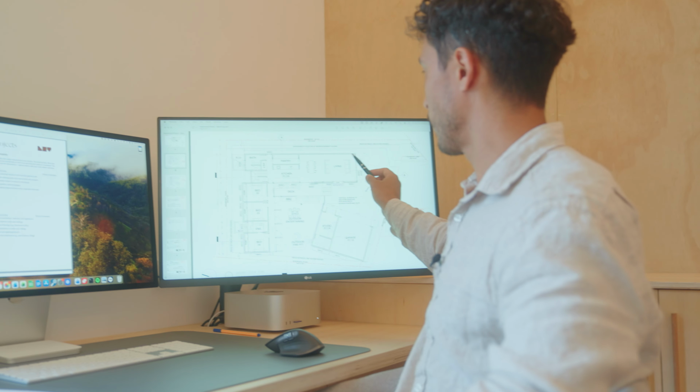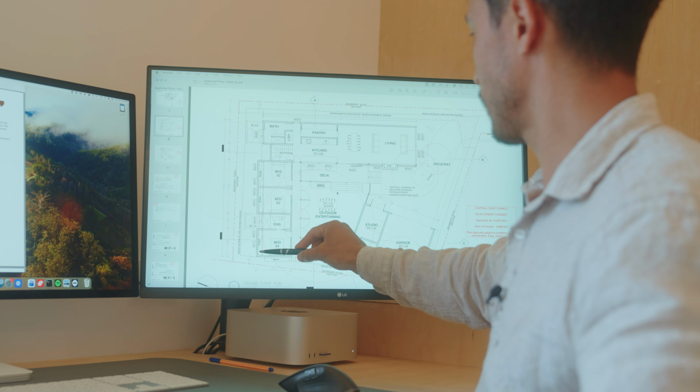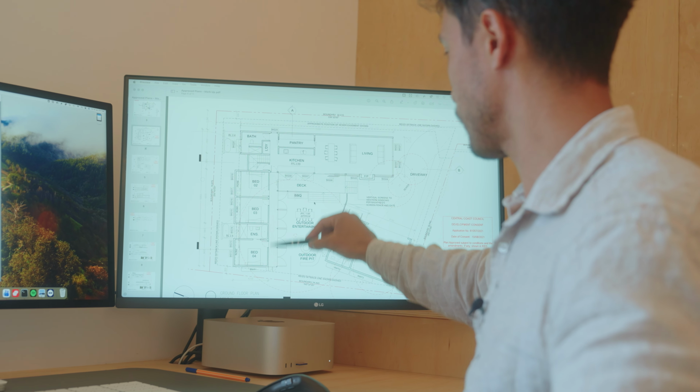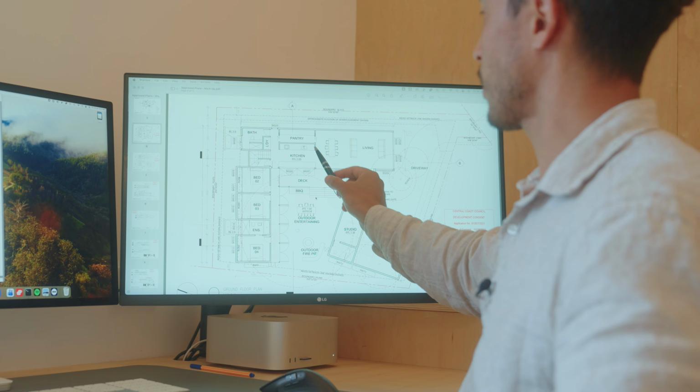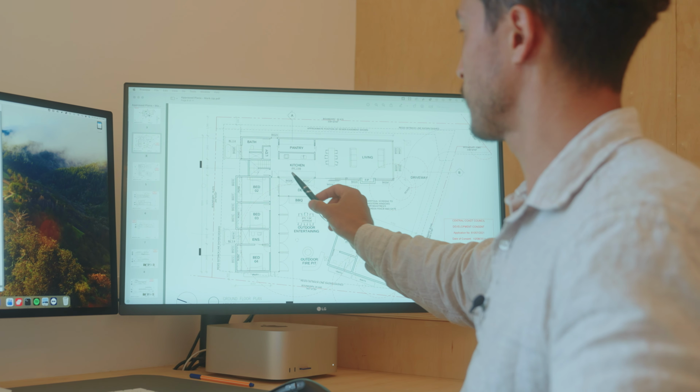The other thing was passive house. So if you're interested in passive house, then we need to understand if you want the HRV, you want the Intello wraps, you want the whole shebang with that kind of stuff. If you're not interested in that, then fine. We just need to know whether you're interested at this stage or not. Okay, now that we've got all that information, we can now start our takeoff. We can measure every length of wall, how much timber there is, how much flooring there is, how many windows there are. And at this stage, again, we don't have a full detail of some of these areas, right?